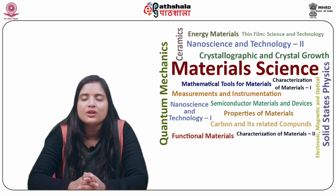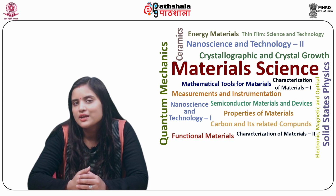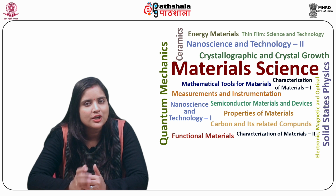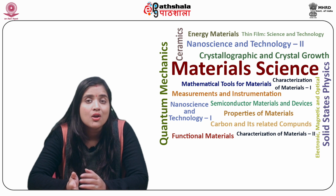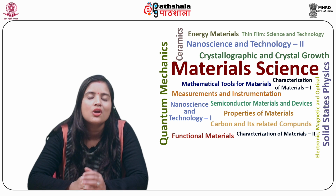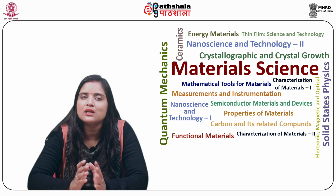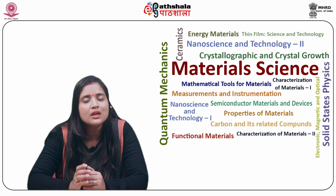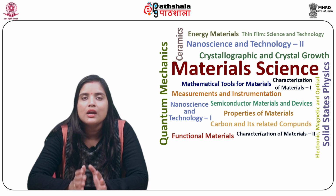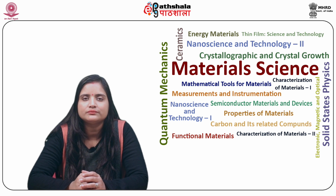Another application is that of electroless nickel on zinc die-cast. In applications which require corrosion resistance along with resistance to chipping and flaking, electroless nickel deposition on zinc die-cast is highly desirable as it circumvents the need for a copper layer.